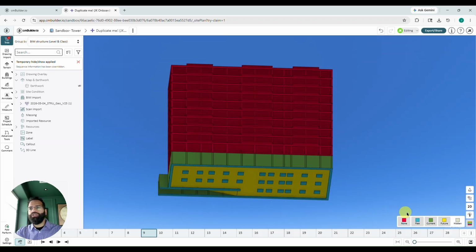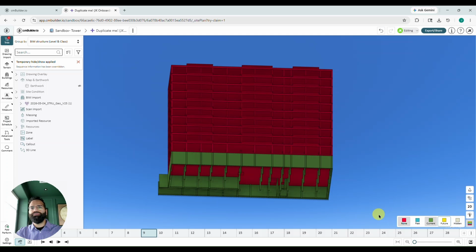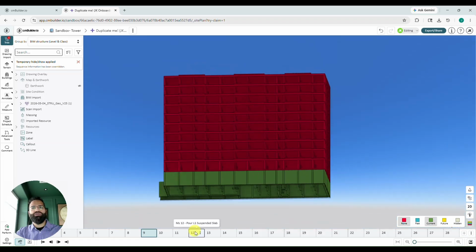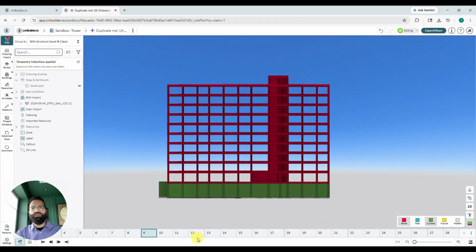So we're also going to turn off the visibility for any objects attached to a past milestone or a future milestone. What this is going to allow me to do is only select objects that haven't yet been attached to the schedule or are already attached to the current milestone. So we're going to go up the rest of our building, attaching the rest of these elements.